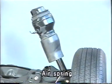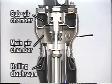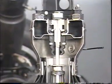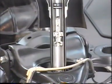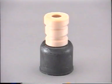Air springs have the characteristics of air in their elasticity or springiness when they are compressed. Air springs provide optimum riding comfort because the air pressure can be adjusted according to the load applied to the vehicle. But the devices for controlling air pressure, such as compressors, are necessary, so the number of components increases and the suspension becomes complex. Rubber springs using rubber's inherent elasticity are used mainly as auxiliary springs for spring bumpers and other suspension components.